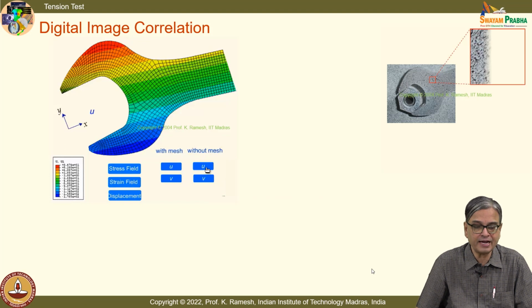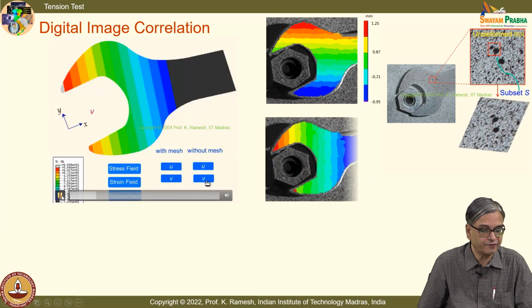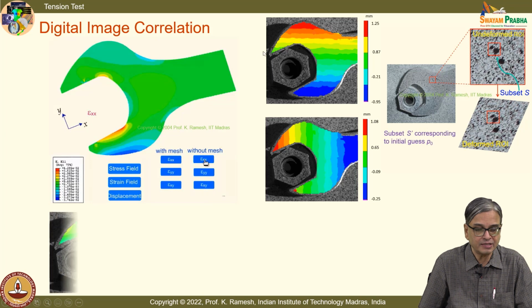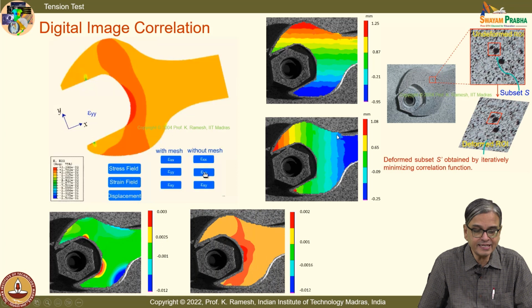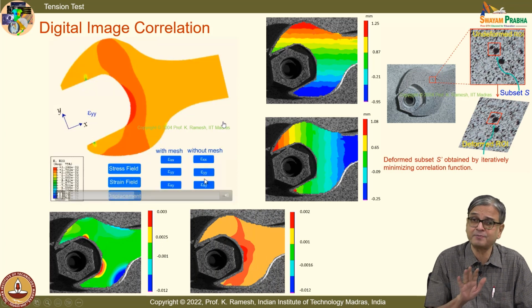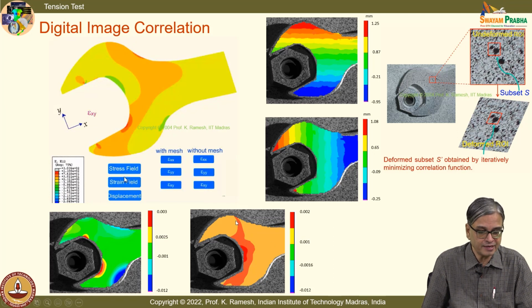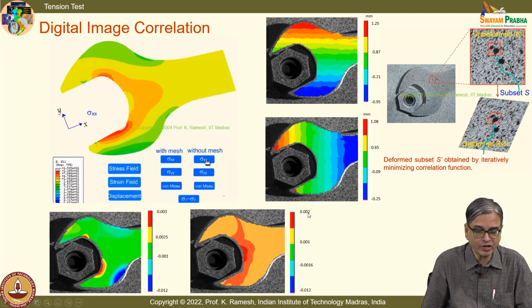And this also compares the result I get from finite element and the result I get from image correlation. See, in finite element I have used a different reference axis. So, these things have to be rotated, that is not done here, but the idea is you see similar patterns in displacement. Displacement measurement is reasonably good, fine. But when I compare the strain, the accuracy is not very high, okay,